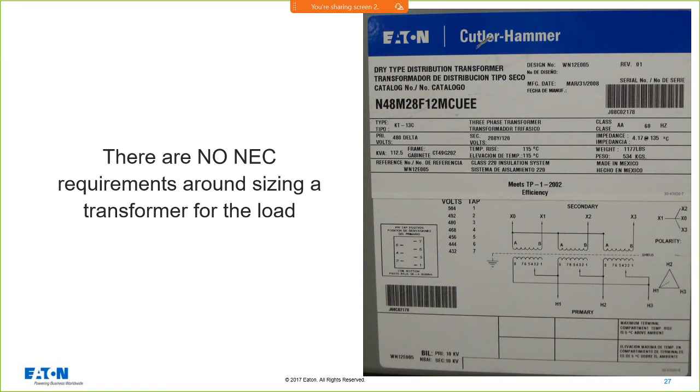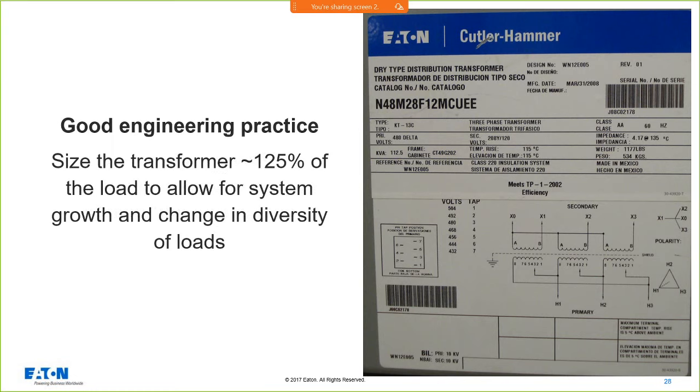We don't have anything that says that a transformer has to be sized for the load that you're going to connect. Now we use Article 220. And from an engineering practice that I am aware of, that I know is published in IEEE, I think the Red Book gives us some information in this regard.